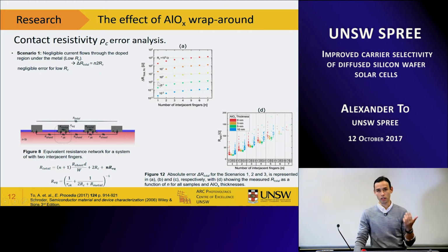So you can get an idea of whether that is going to affect your linear slope by comparing particular values of contact resistance relative to the R total value that you actually probe. Essentially what you find is that if you have a very good contact and your contact resistance is low, this term here drops out and is a negligible addition to that linear fitting, because it's not really adding much to those points along the curve.